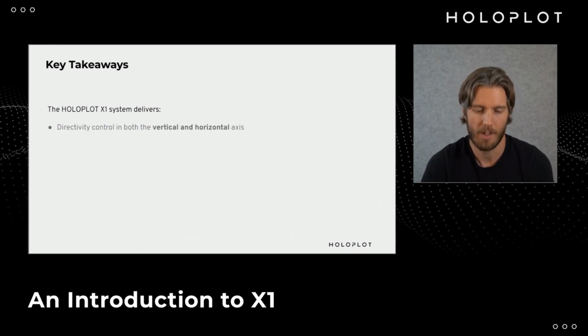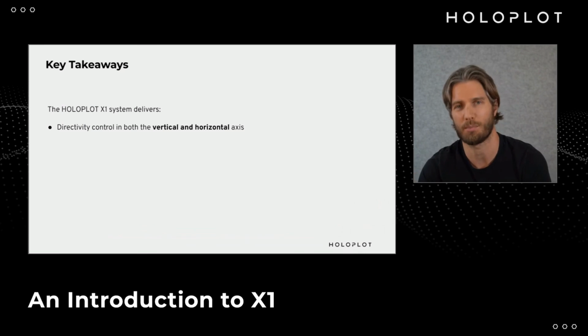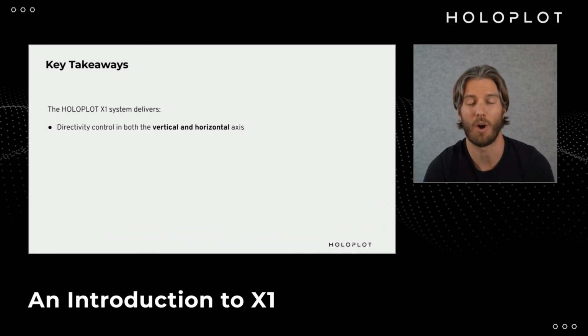What's it doing? Directivity control. We kicked off with this quest for directivity control and how we achieve that. And we've seen the evolution of the loudspeakers as it moves through that, and us now bringing in the matrix array, the ability to control in the vertical and the horizontal. This precision that we now have to focus the energy into the audience areas, to create this homogeneous coverage across the audience areas and achieve this spectral uniformity across these areas, is something that's not been achievable before. And you really do drive up the intelligibility of the sound within your venue.